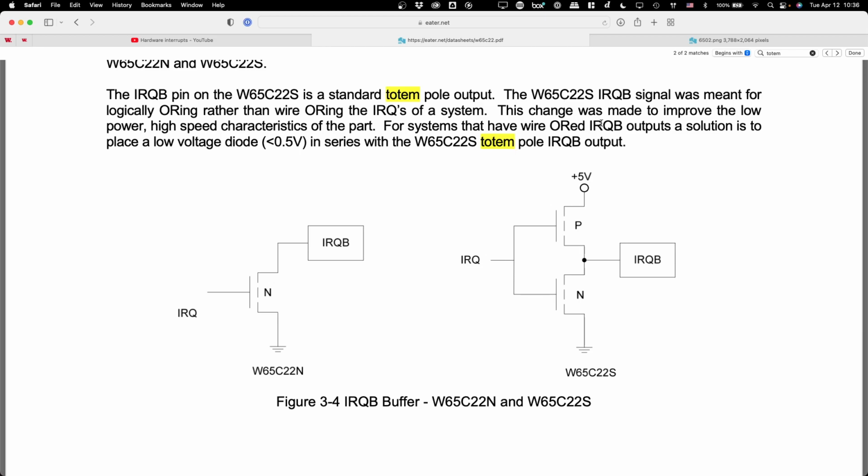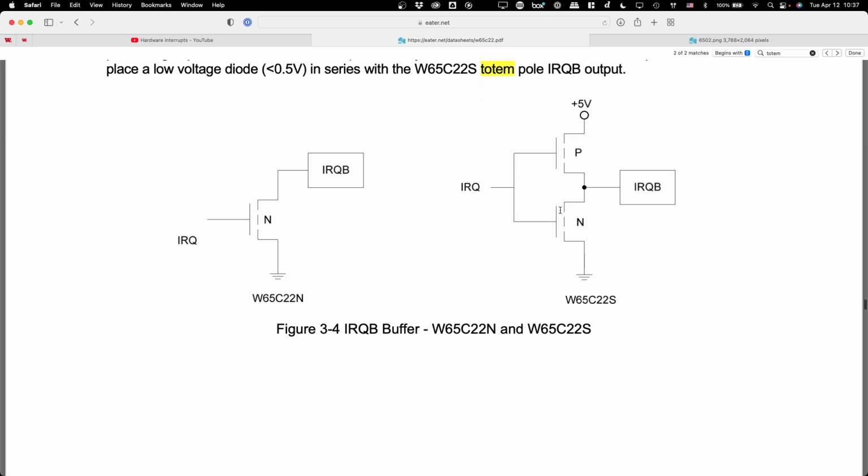Any of them turn on, it'll signal one of the pins to be on. Okay. Yeah. So the IRQ. So okay, the difference between these two diagrams, right, is so the original 6522 and 6502 and all of those dudes were all fabricated using an NMOS process. Okay. And so essentially they were using N-type transistors, only N-type transistors. And the reason that processors back in the day were made using those only is because those ones worked faster and were more reliable to manufacture at the time than the P types.